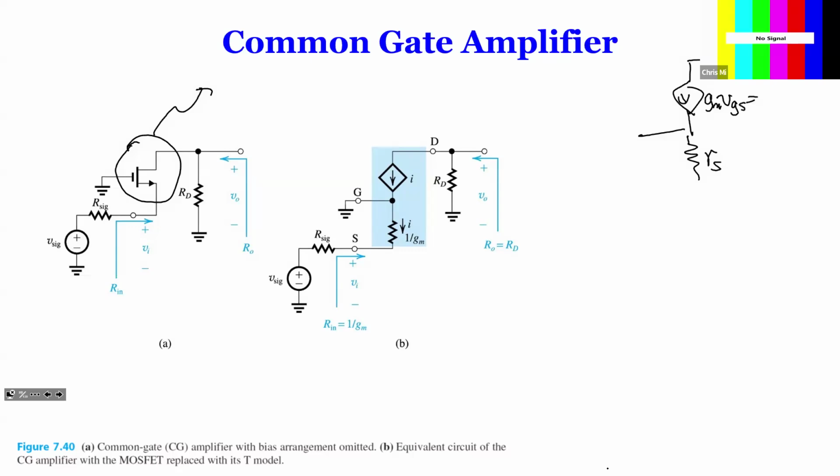Or sometimes we simply use the I to in place of that. And so this is your model. So your model top is your D, and bottom is your S, and this is your G. So given that, now you find the model, now we look at what are the things connected onto each of these terminals. So if you look at gate, apparently in this case, gate is grounded, so we'll simply ground it.